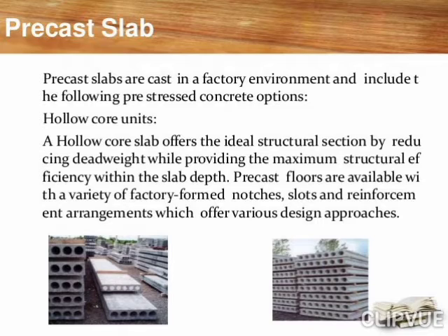Hollow core units. A hollow core slab offers the ideal structural section by reducing deadweight while providing the maximum structural efficiency within the slab depth. Precast floors are available with a variety of factory formed notches, slots, and reinforcement arrangements which offer various design approaches.